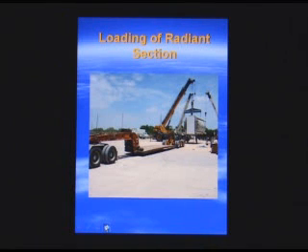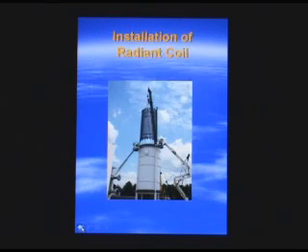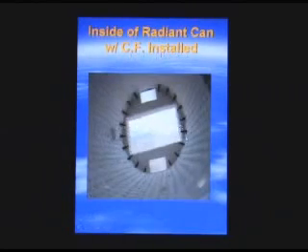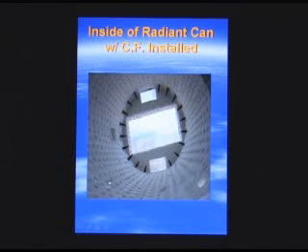Does the ceramic fiber insulate the heat? Oh yes, there's very good insulation. The casing of the ceramic fiber, it's required that under worst case ambient, let's say hot day, no wind, the surface temperature of the carbon steel on the outside be 140 degrees maximum. So you can basically touch that.